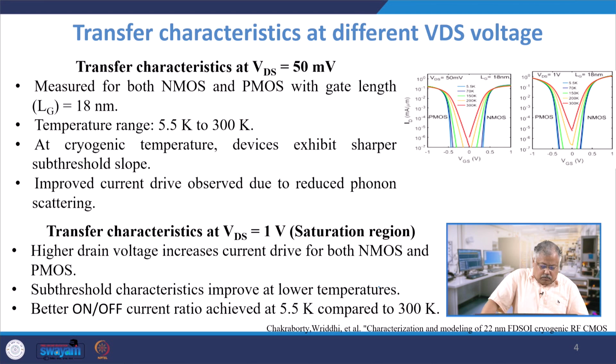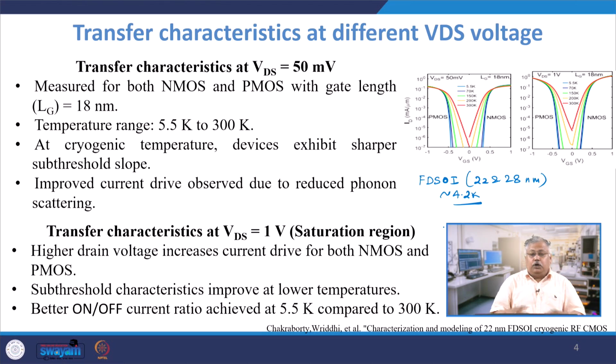Okay. Now, this is basically an ultra thin body, UTB, device, and the commercially available FDSOI CMOS, typically at the 22 and 28 nanometer tech node, has been investigated at approximately 4.2 Kelvin temperature in this paper. They have actually looked into device variability issues and self heating. So both self heating effects and device variability effects have been taken into account.